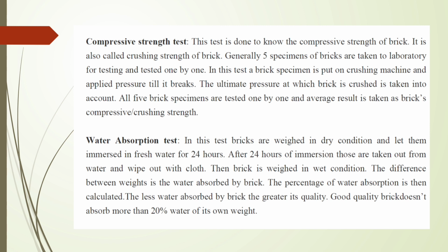Water absorption test. In this test, bricks are weighed in dry condition and let them immersed in fresh water for 24 hours. After 24 hours of immersion, those are taken out from water and wiped out with cloth.